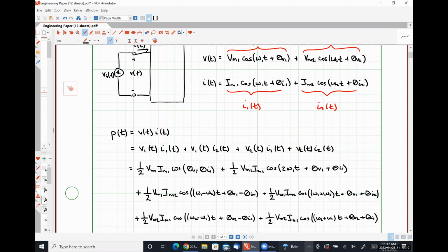So does that mean that theta portions should just add with those common frequencies? So you wouldn't really add them in the time domain per se. And the reason why I say that is because the math would be very, very difficult. Because if you had, let's just say, sine 2t plus 5 degrees, or cosine 2t plus 5 degrees, and cosine 2t plus 10 degrees, how do you add those two together? Well, it's kind of complex numbers. Yeah, complex, okay. Thanks. So you can't just lump it together as a single term easily here. You would have to use a complex number representation in order to do it. But they do represent oscillations at the same frequency, so that math is possible. But in a time domain representation, this is going to be the easiest way to represent it.